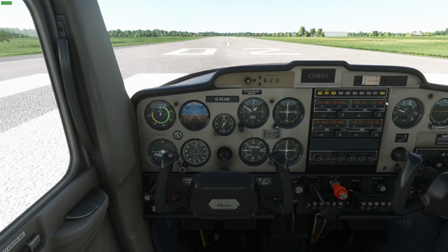Now if this is the runway, we're going to be doing a circuit. So we're going to take off on the runway, turning left 90 degrees. So that'll be a heading of 290, climbing another 500 feet up to 1,000 feet, turning left again, heading in the opposite direction that we are now, which would be 200 degrees at 1,000 feet above circuit.